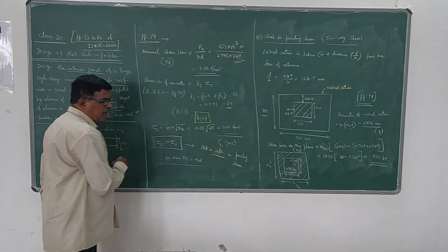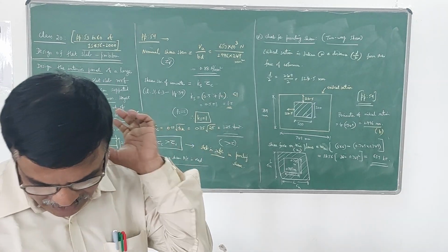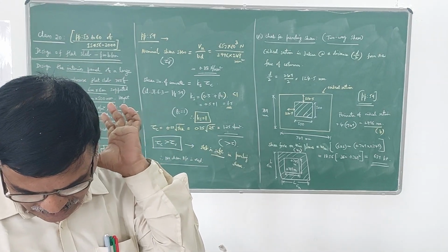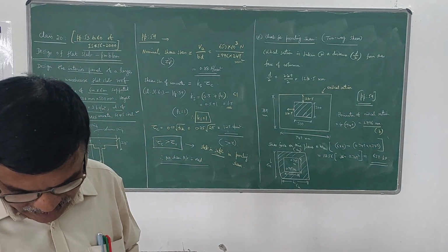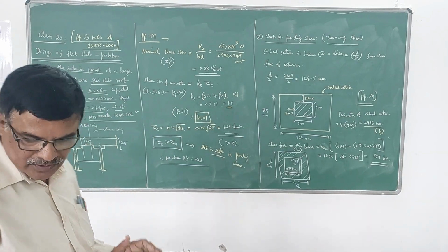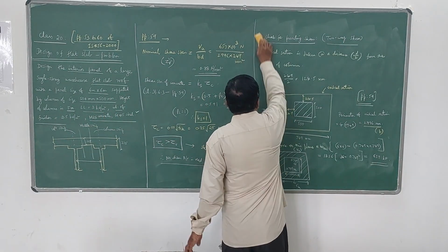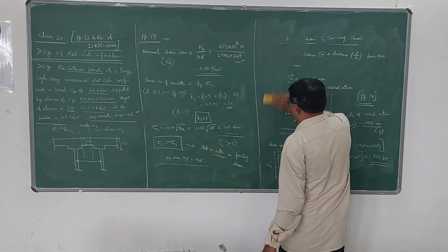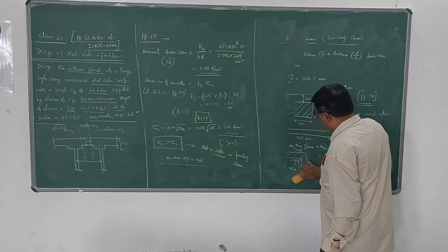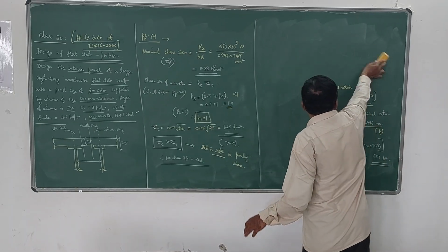Usually slabs don't carry much shear force, so shear reinforcement is not required here. Now the last step is reinforcement design. For that you can use SP16. They will provide SP16 in the exam, so you can directly see the chart and get the percentage.